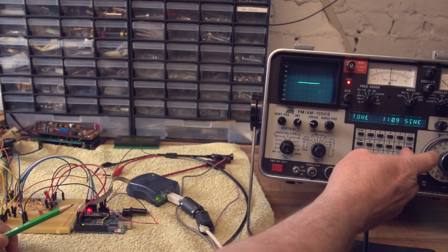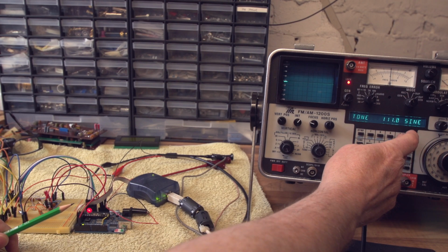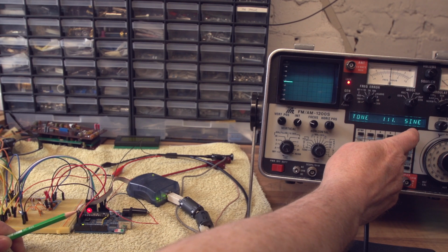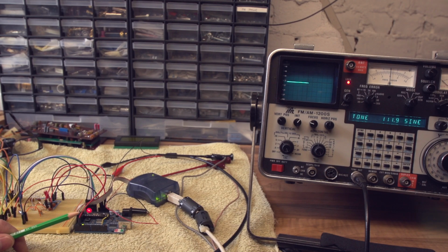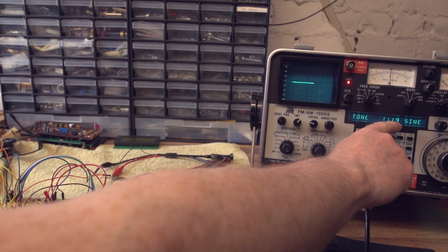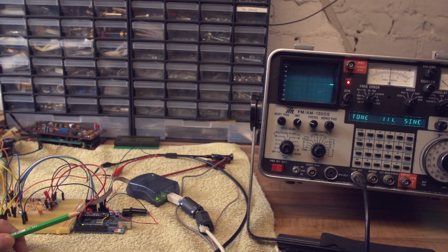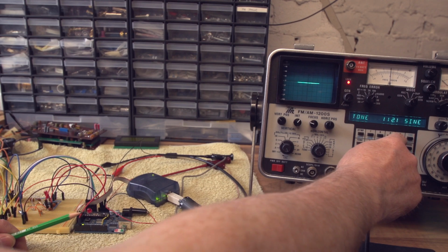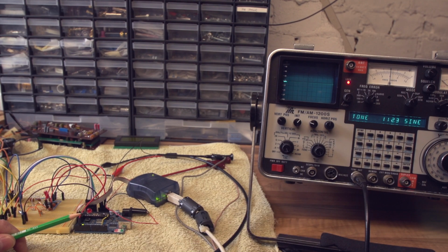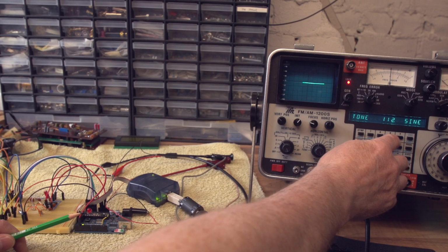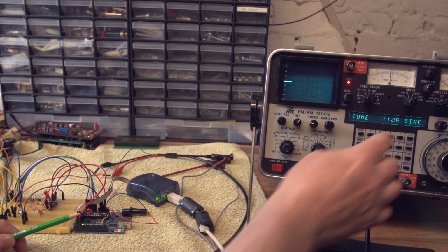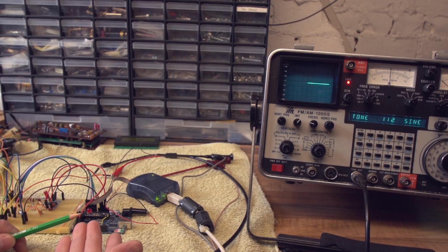So what we can do is alter this and take it up, so it's 111 Hertz, still red, still red. I'll keep going up until we lose the LED. It's just starting to give up now, so that's right on its limit, and that's 111.9 Hertz. So that's an undetermined state. If we go any higher, I'll just keep going up a little bit. The LED's almost off completely at 112.3, 112.6, it's gone. So that's the upper limit of that particular channel.